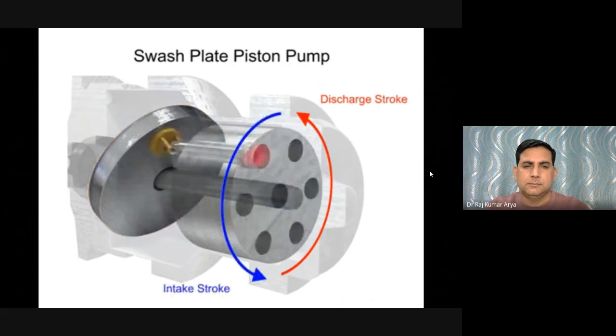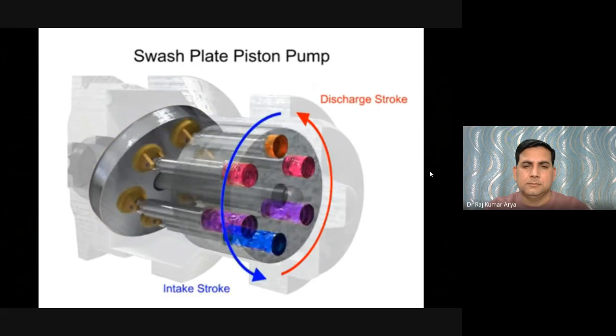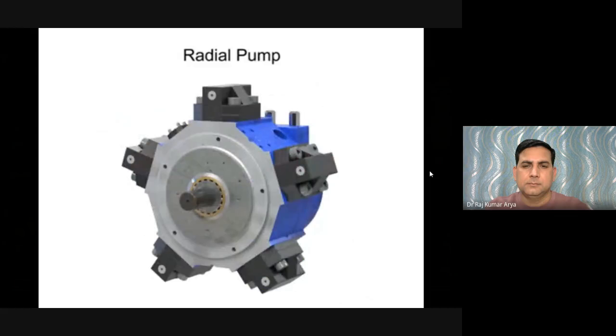Piston pumps, in general, are manufactured with closer internal fits than other pumps. This means that internal slippage can be less, so that they operate with reasonable efficiency at pressures both too high or too low for the operation of other pumps. Radial pumps are designed so the pistons stroke in a direction at right angles to the shaft.